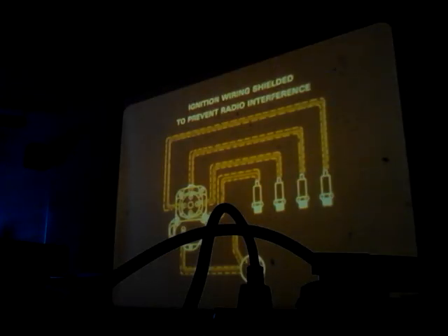To prevent this unwanted noise, the entire ignition system must be shielded. The magneto, the spark plug, and all of the wiring is usually encased in a metal covering or shielding. This intercepts radiated energy and directs it to ground, where it cannot cause any interference.